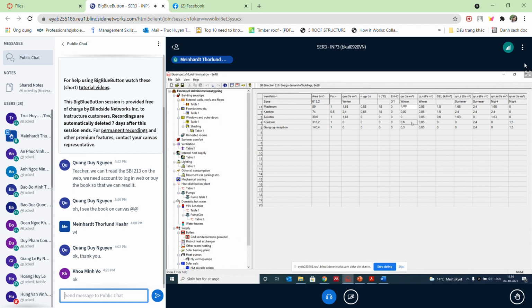For the offices, the hall is a bit higher because it's the infiltration plus the natural ventilation that they designed, so you can actually get some ventilation into the room. This is during the night time, so when the building is closed, it's also influenced by the untightness of the building.